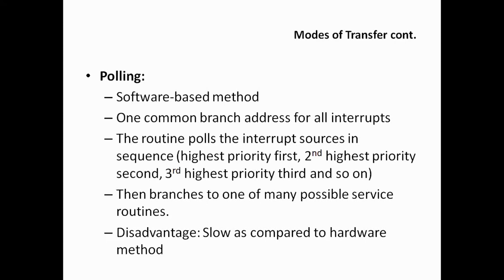And if there is another device C which has a lower priority than the keyboard, then below there will again be else if the device is C, then it will be addressed. So if else statements will be kept in a particular program. This program will do the polling. That means it will decide which one to address first, which second and which third. The thing which has the highest priority will be first, second highest second, third highest third, and so on.